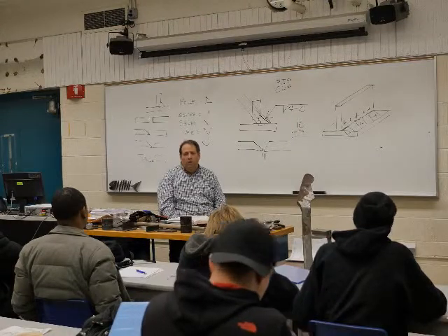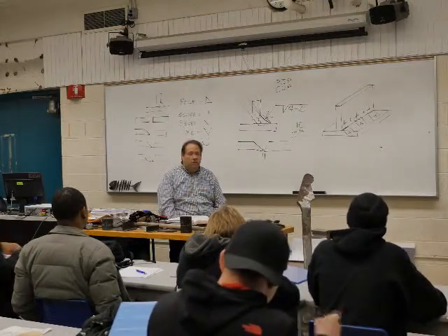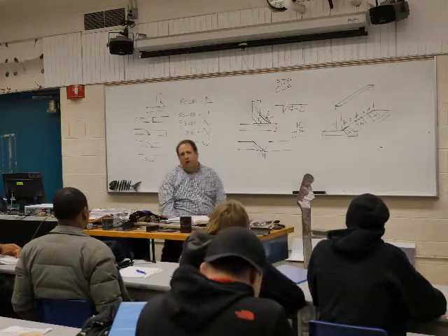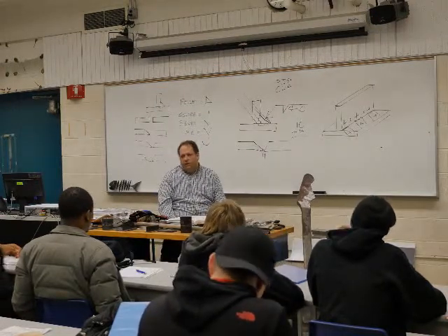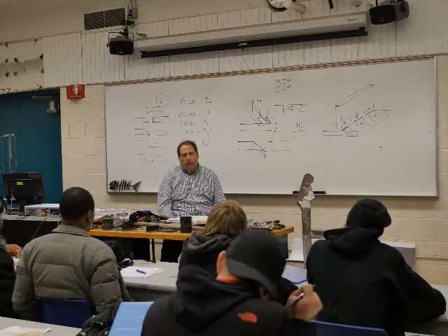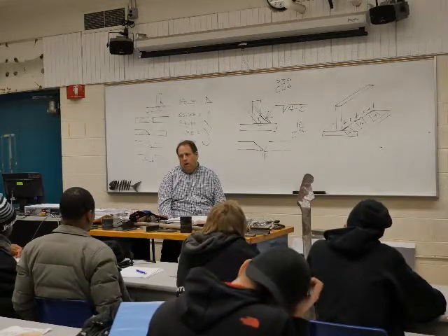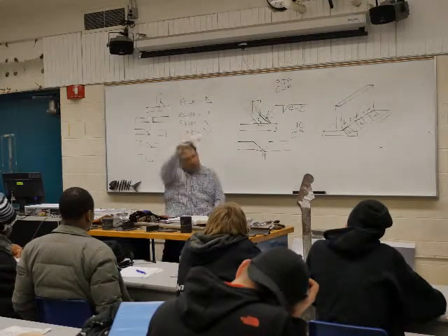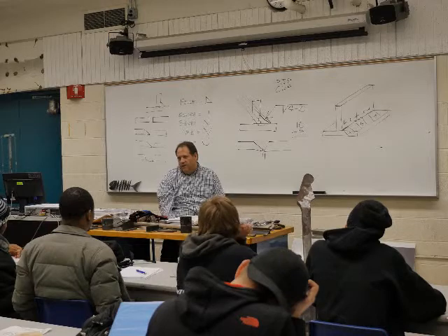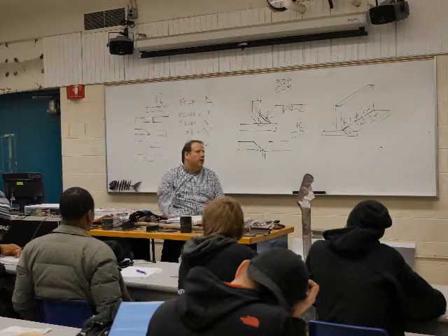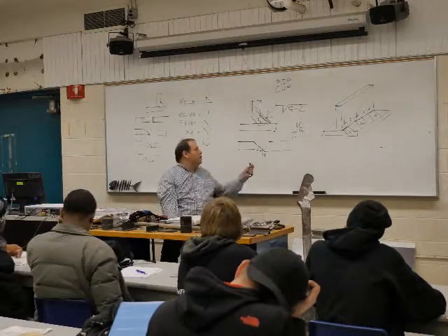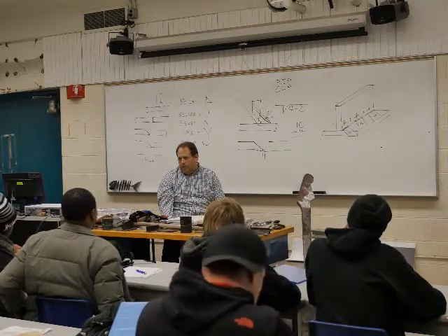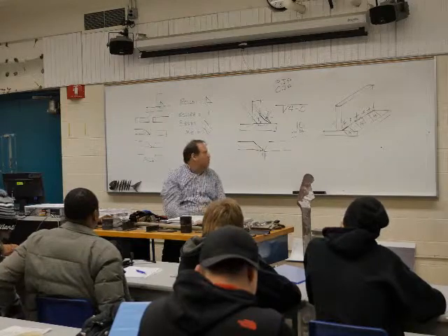Because if they don't have any kind of practical welding experience, and they say that they want an 1/8" gap right there, but we want you to use 3/32 rod, it's not going to work. It's going to be too big of a gap. You're going to be sitting there filling this huge area up. It's just not going to work. So I would prefer that you are actually setting your root opening. So that's why I'm not really going over that.